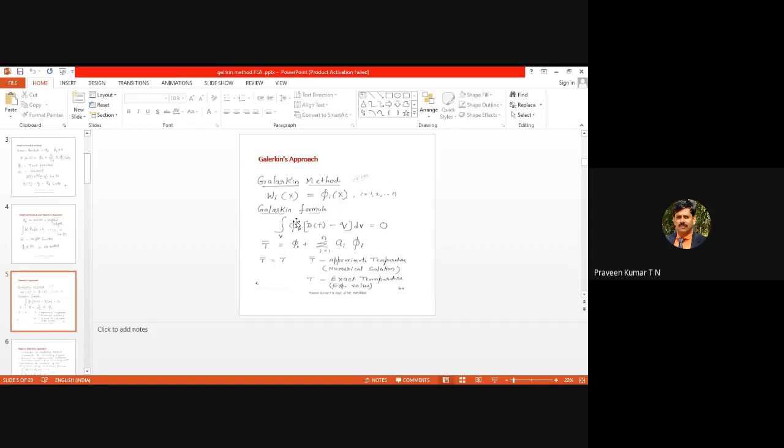So when you come to your derivation, you have to remember T1 and T2 refer to nodal temperatures. Those are the actual temperatures. But approximate or virtual temperatures are referred to by xi1 and xi2, or this xi, which in our derivation you write as N into xi. Here N is N1, N2, a row vector, and xi is xi1, xi2, xi3, etc. Those are the virtual global vector, and we have this differential equation, equation 1.